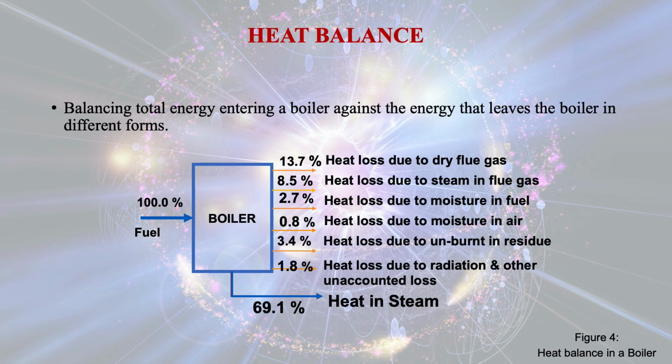For this case, around 13.7% is heat loss due to the dry flue gas. 8.6% is heat loss due to steam in flue gas. 2.7% is heat loss due to moisture in fuel. 0.8% is heat loss due to moisture in air. 3.4% is heat loss due to unburnt in residue, and 1.8% is due to heat loss, radiation and other unaccounted losses.